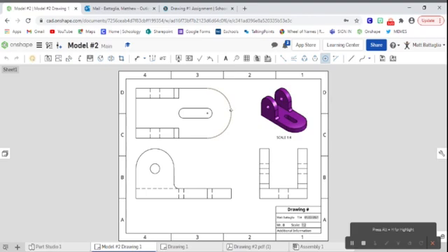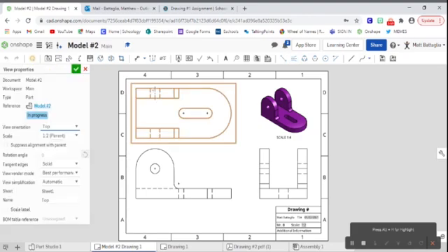For the center mark, we're going to go over all of our curves, and we're going to be clicking when we get this nice orange kind of highlighted line that you can see. So once again, I'll click, and I will click, and that does all of our center marks. Let's go ahead and take a look at the center line tool. So for edge to edge, that's exactly what it's doing. You select on one edge, in this case, the hidden line of our hole, and you select on the other edge, and it puts that great hidden line right in between there.